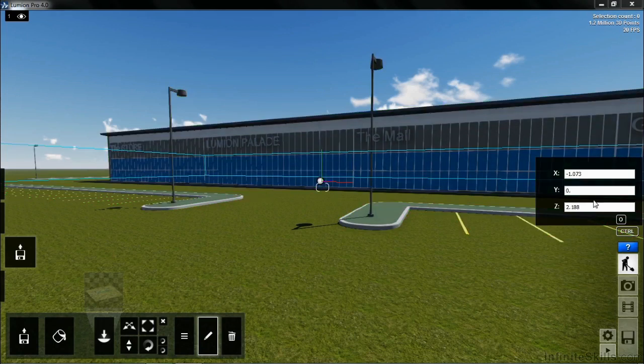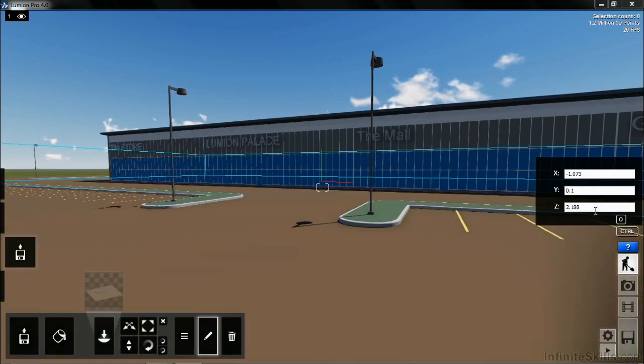After clicking on that white dot, you'll see an X, Y, Z position. In the case of this project, the Y position will control the up and down. Here where it has Y and it says 0 point, change this to 0.1 and see what happens. When you do, you'll see the entire building, the entire imported object, will raise itself up. And this works for any imported object in Lumion. If you select the object, go to its properties, click on the little white dot, you can then adjust its exact location on site by going to the X, Y, and Z of the project. And that's the process to bring in a Revit or AutoCAD or any kind of model into Lumion.